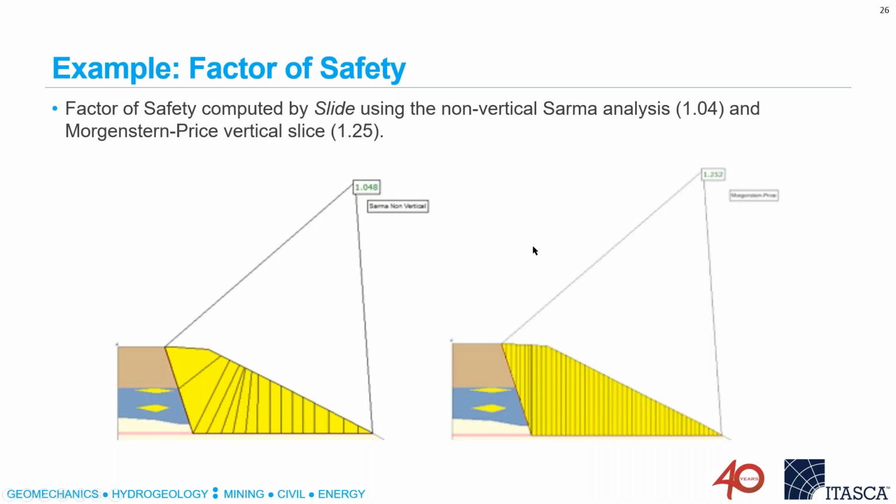And we're going to come back to this in a couple other cases to highlight just how important this internal deformation can be. And it is for this reason that a lot of limit equilibrium methods tend to overpredict stability if there is some mechanism for internal sliding and deformation.